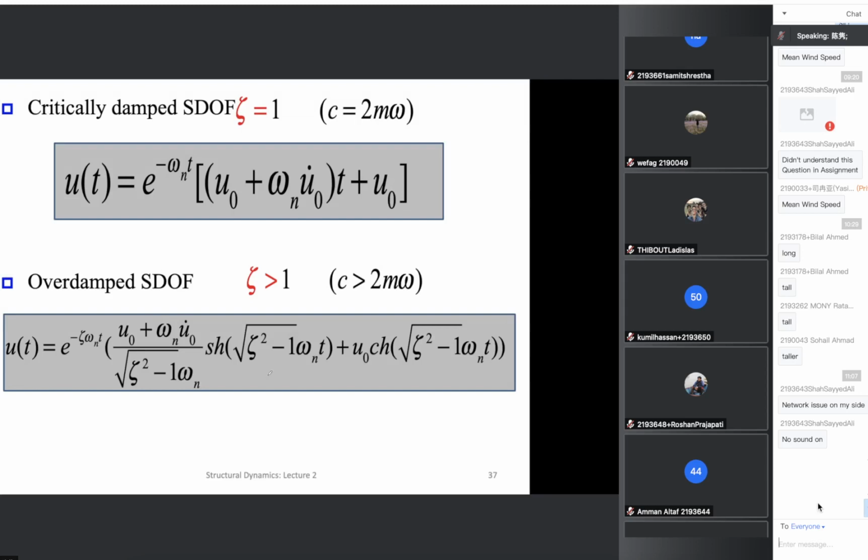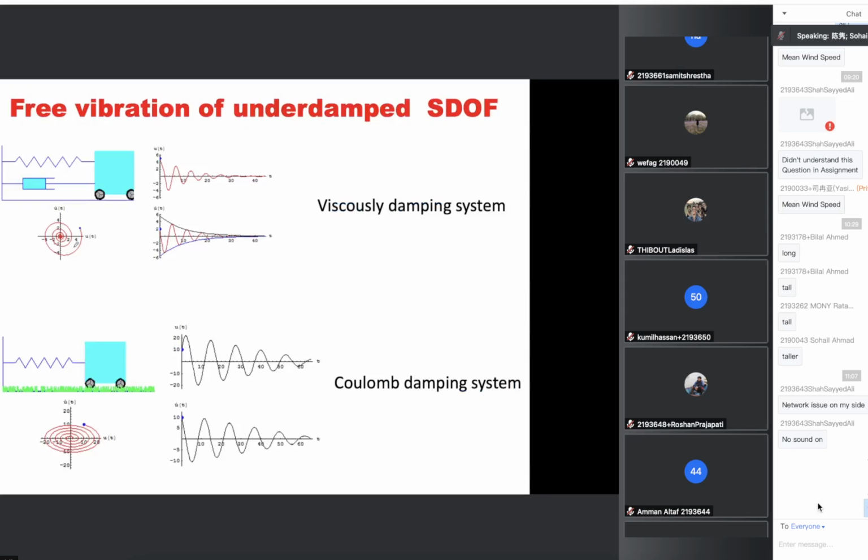If the seat is a lightly damped system, it will vibrate like this after each bump. So it should be an overdamped system, which means after release from the initial displacement and velocity, it just slowly goes directly back to the original position. It will not start vibrating for a while.